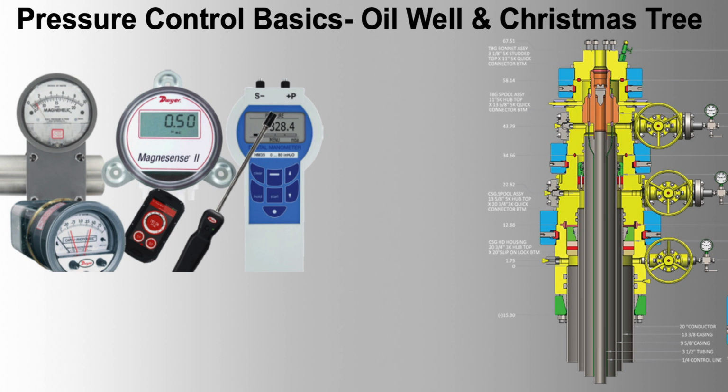4. Example 4, surface pressure sensor for hydraulic fracturing. Instrument type, piezoelectric pressure sensor. Accuracy, 0.25% of full scale. Material, Monel K500 for sour gas resistance. Installation, surface installation on the fracturing manifold with quick connect fittings for ease of installation and removal. Other criteria, real-time data transmission, explosion-proof housing, high-frequency response to capture transient pressure spikes.